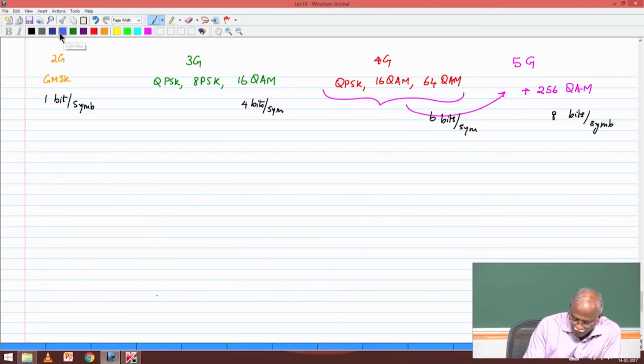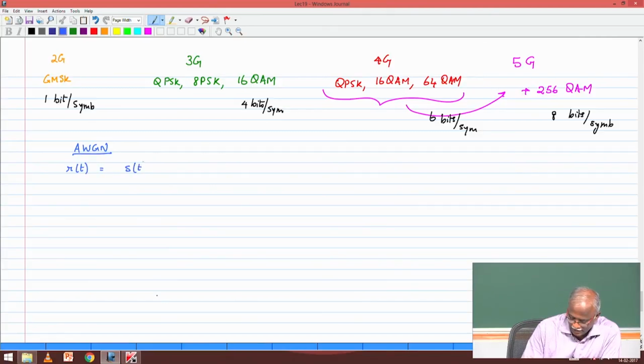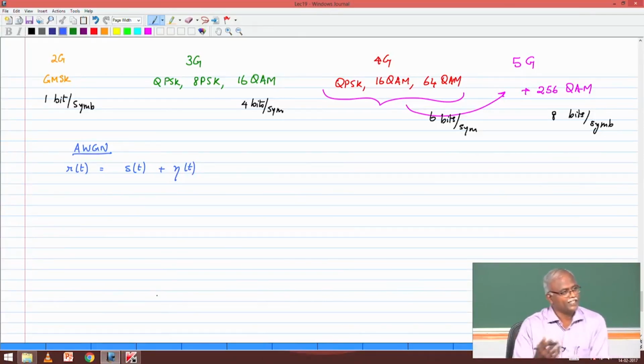Now let me move on to highlighting one more important element: the received signal in AWGN. r(t) is the transmitted signal plus the noise, that is, the additive channel noise. So detection is straightforward, you have already done it in your computer simulation example.